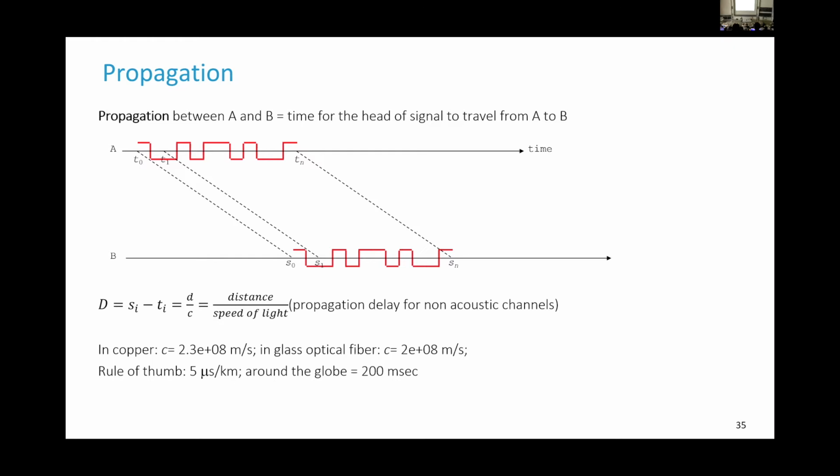For example, if you use Ethernet at 10 megabits per second, this is literally what happens. If you measure the voltage of the line, you will see oscillations between -5 and +5 volts. And this is literally how some very primitive systems send information. Now, today's systems use much more sophisticated physical layer coding schemes, but it doesn't matter. For us, the important thing is that the bit rate gives the transmission speed, and it gives the time it takes to transmit a number of bits. This is how much time it takes on the horizontal axis.